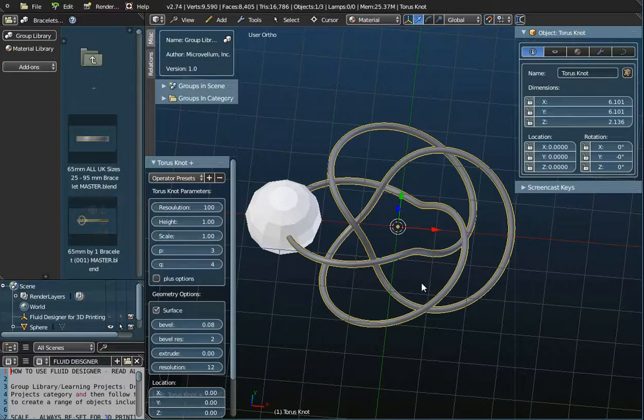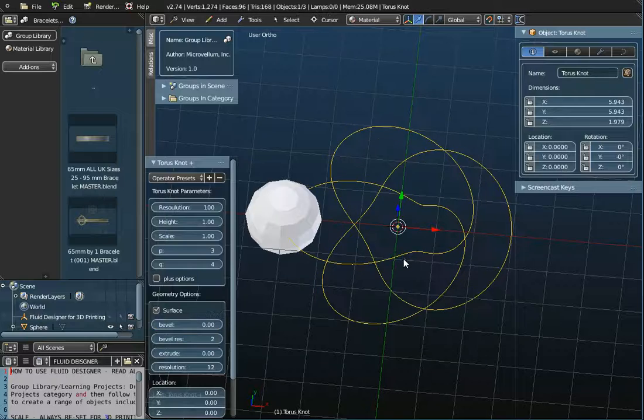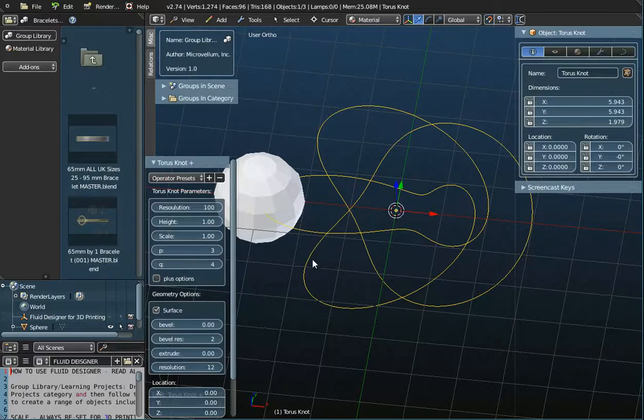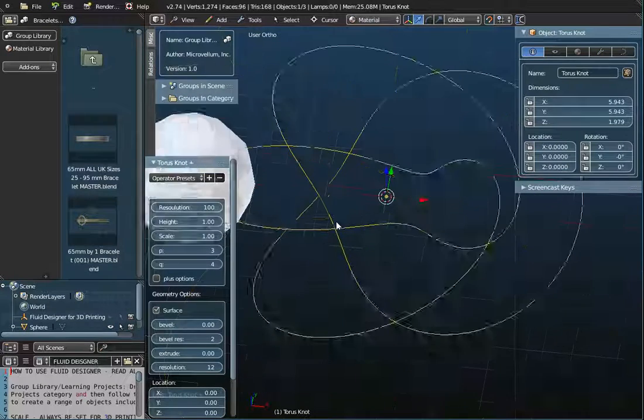Now where is the curve itself? Well, if I change this value here, this thing called the bevel, if I type in there 0, that's actually my curve. The bevel is what's wrapped around the curve to make it an object and to make it 3D printable. The actual curve itself is that.